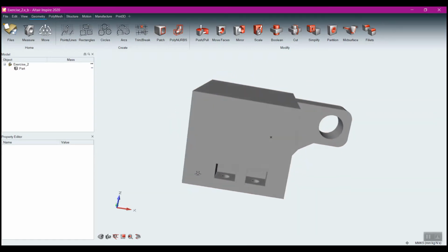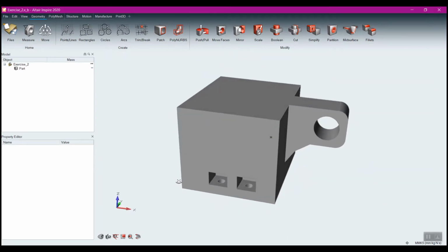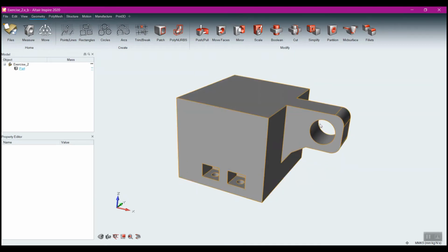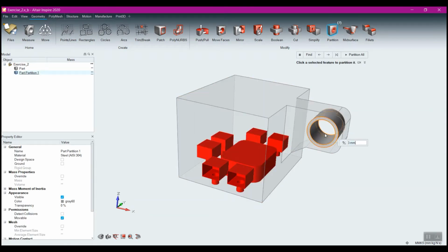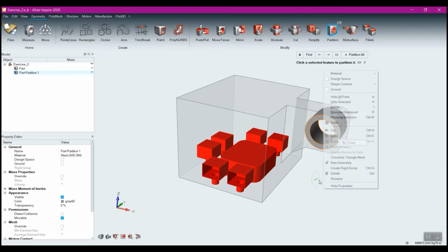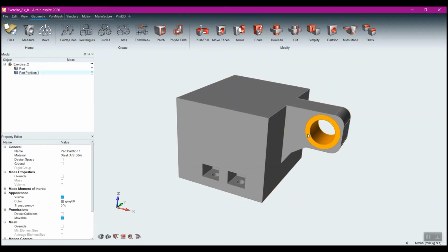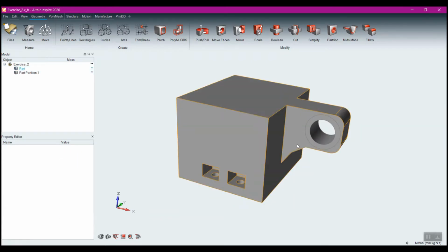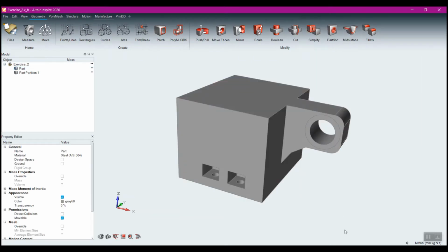Now, there are some aspects of this that have to be there. What we need to do is protect things like this mounting sleeve here, and also, as mentioned in the geometry, we can do that through partition. I can partition that, and maybe we'll make it 5 millimeters thick. And now what happens is this is going to be its own separate piece from this right here. And ultimately what we're going to do is we're going to select this as design space.